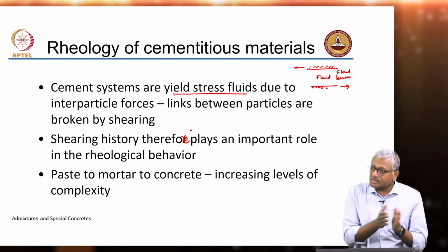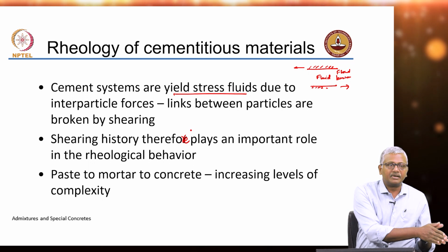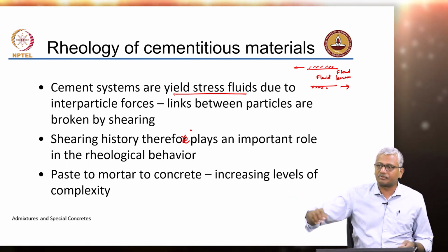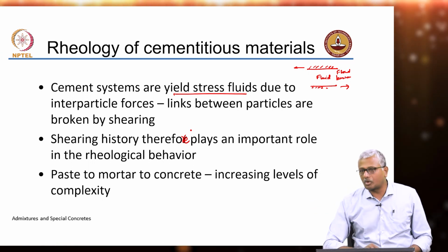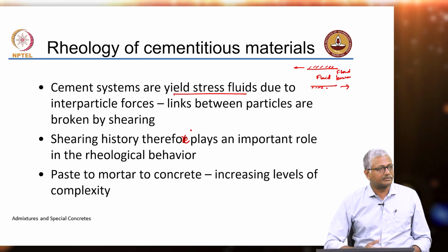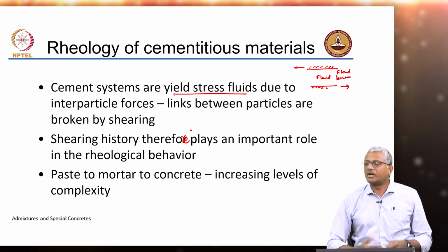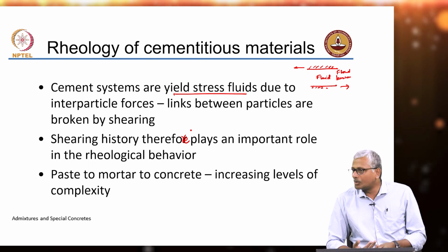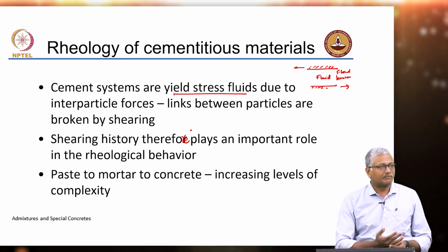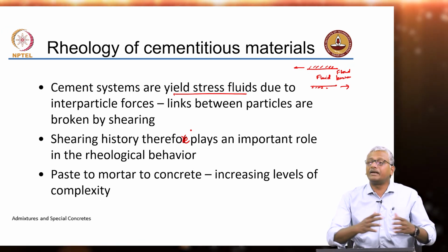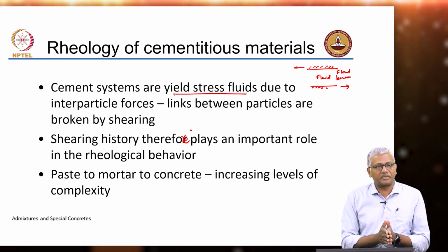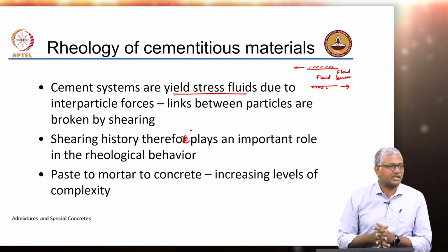That is why translating rheology studies of cement paste to workability or rheology analysis of concretes is a very difficult proposition. And in fact, most people who work in rheology try to do this some way or the other, because working with a paste system is easy. You don't have to waste too much material. It can be done with smaller systems. With concrete, everything is scaled up and it becomes expensive. So because of that, people want to study on paste and extrapolate to concrete, but it's not very easy to do that.